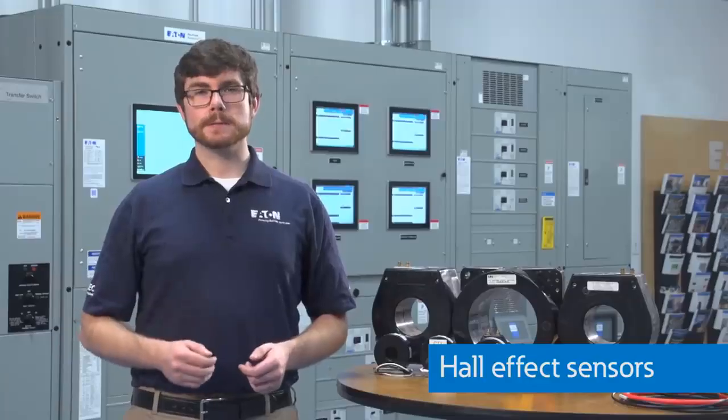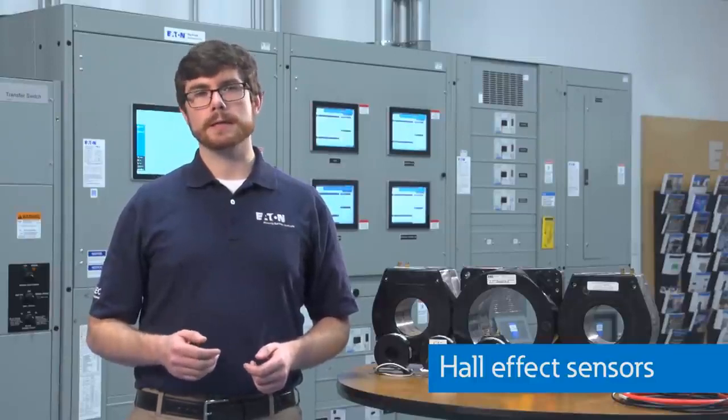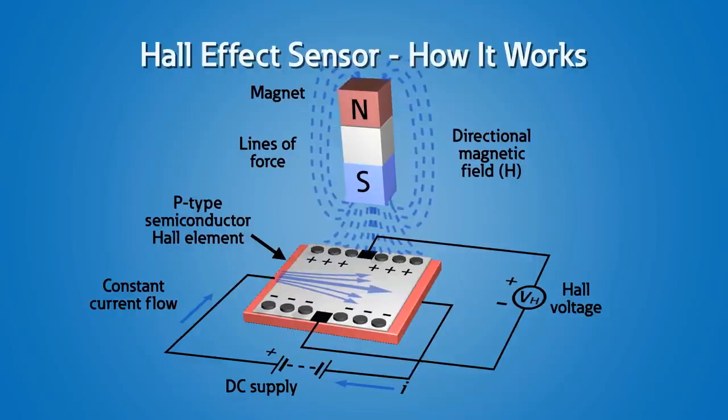This method can be used to measure both AC and DC current. However, as the current that is being measured increases, implementing this method requires the use of large, high current rated, and low ohmic value resistors that requires making a break in the circuit and adds an additional electrical component to the system. Just as shunt resistors can measure both AC and DC current, Hall effect sensors can also measure AC or DC current. Hall effect sensors require an additional DC supply to produce a constant current flow in a semiconductor, creating a constant magnetic field.